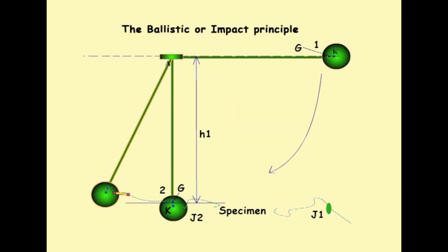When the pendulum is released, it swings downwards and when nearly vertical begins to pull on the specimen. Continuing its swing, the pendulum stretches the specimen, breaks it, rises to position 3 and finally comes to rest in position 2. The work required to break a specimen can be calculated by considering the height to which the center of gravity rises after the break.